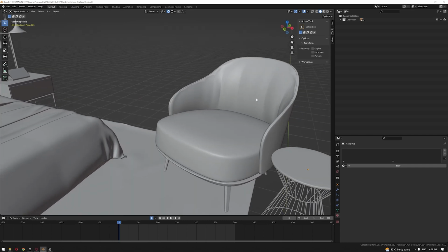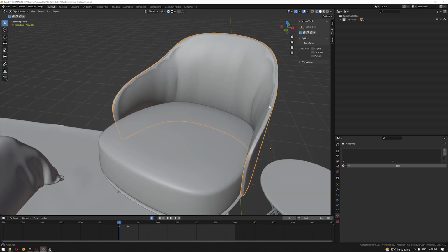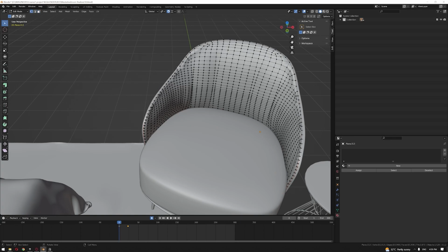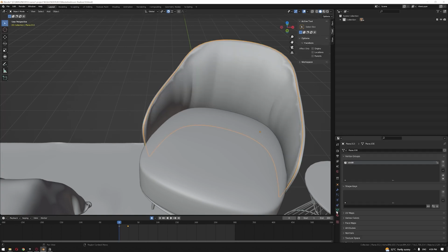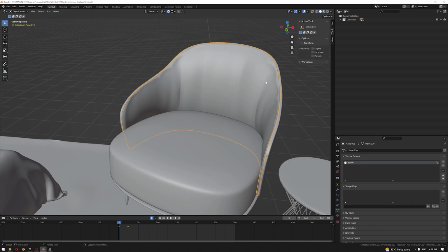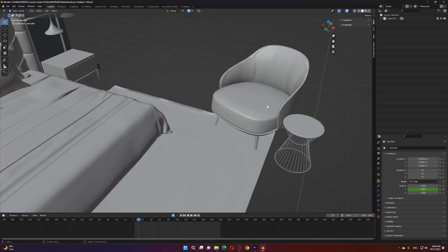Then for the final result, after editing all of the other elements, we basically also took a copy of the inner faces and selected all the vertices around this shape and made them a selection group, or a vertex group, to be isolated from the cloth simulation, added the cloth simulation to this part and simulated. And with this, we have finished part 1 of this tutorial.